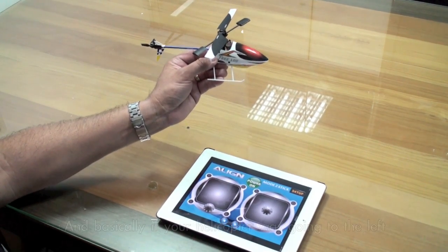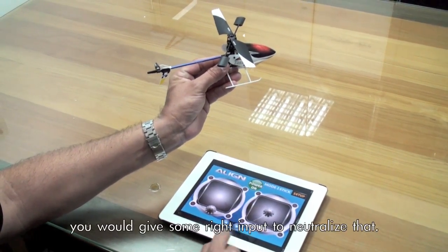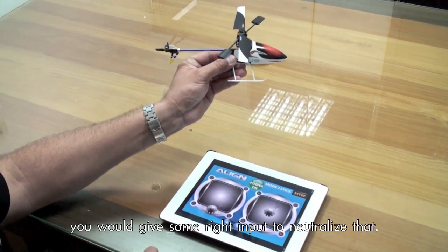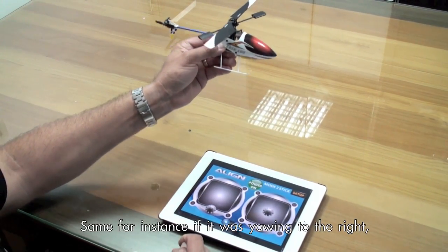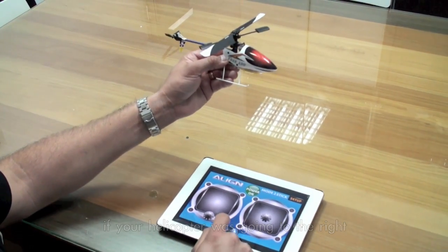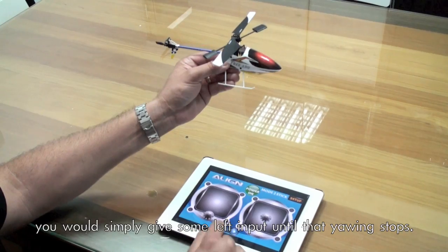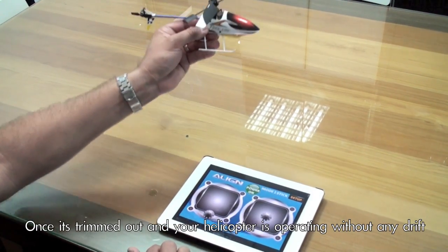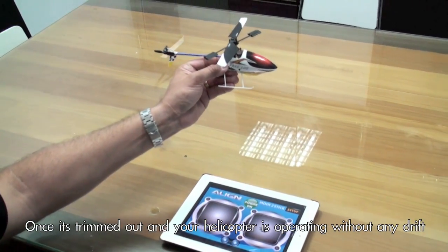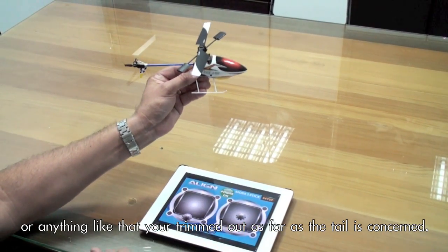And basically, if your helicopter was going to the left, you'd give some right input to neutralize that. Same, for instance, if it was yawing to the right, if your helicopter was going to the right, you'd simply give some left input until that yawing stops. Once it's trimmed out, and your helicopter is operating without any drift or anything like that, you're trimmed out as far as the tail is concerned.